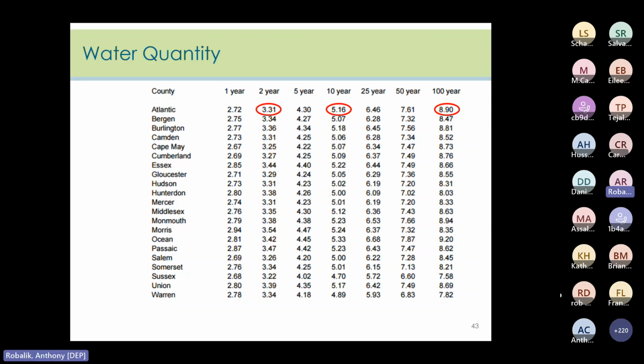So here's a chart for all the various counties, and those numbers pretty much match up with what's here in the chart. So this may be actually where they got those values. They could have also gone to NOAA's website, which has more accurate rainfall data for the exact site, and that's the preferred option, but either one is technically acceptable.